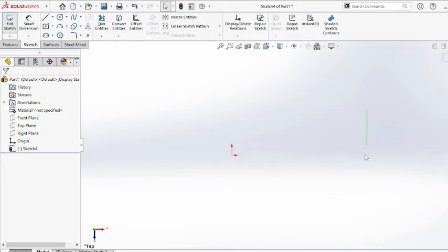You can press the left click, you can drag left side, green color is there. This is called cross polygon. This is used for selection in AutoCAD or this software also. So you can click and drag right side, blue color is there. This is called window polygon. So these both are used for selection. But what is the difference for selection?